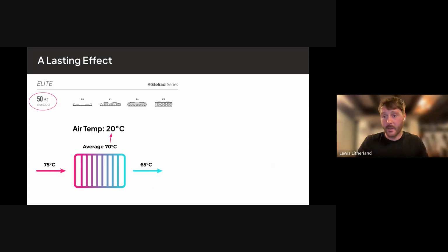So if you look at your radiator outputs, a lot of them have got apps now where you can adjust this. But if you were just to buy a catalog, it would say Delta T50. And when we get into the radiator module, this will become apparent as well. It's all based off that old non-condensing model of a 75-degree flow temperature, as it says there.